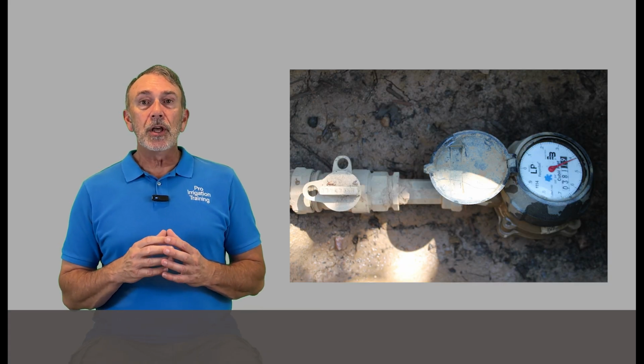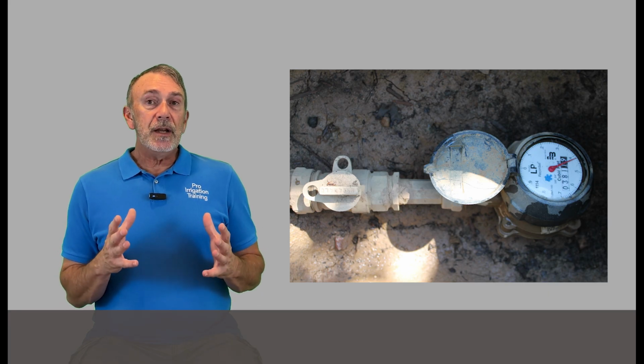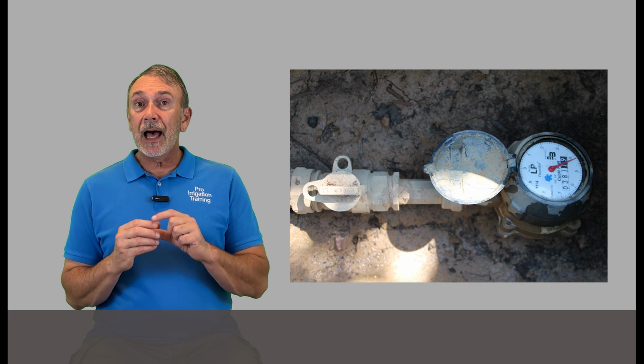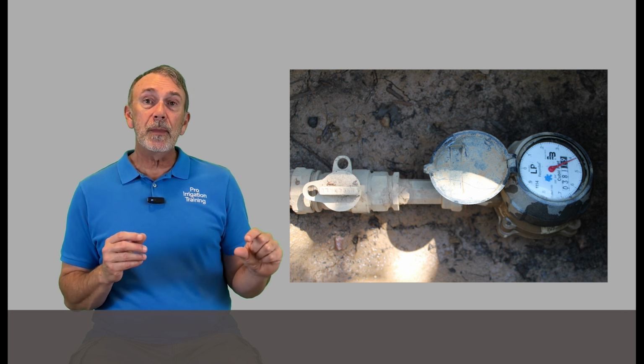And so what we're constrained by is the size of that water meter and the size of the tubing that connects the water meter to the main water line. Here we have 4-inch water pipes out underneath the street, and then we connect to that by copper tubing to a brass and copper water meter. And so usually for a residential system, that meter is probably going to be either 5/8 inch or